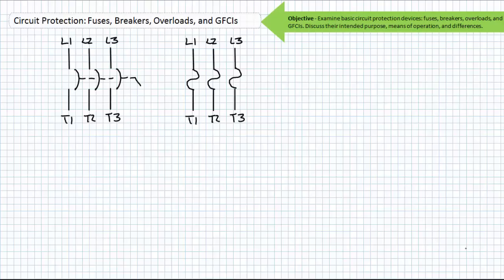The circuit breaker is a single point of control that opens or closes all three sources simultaneously. The fuse is not so much. One fuse could blow, and the other two fuses still function, leading to an undesirable upsetting of the balance between the three separate phases, known as single phasing. Single phasing is normally associated with high current draw, reduced performance, and a uniquely horrible sound produced by a three-phase motor.